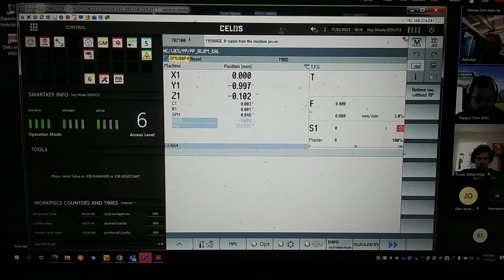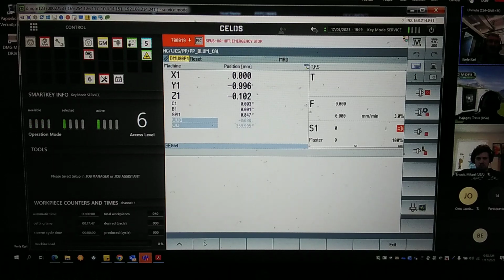This is for, let's say, detecting, by the next soft key assignment on position F1, the vibration. Let's say here we measure always during every program run, is the spindle okay? Here you see the several activations of measurement, also here for the spindle bearing. Also, let's say we can switch the vibration limit off or on, and so on.